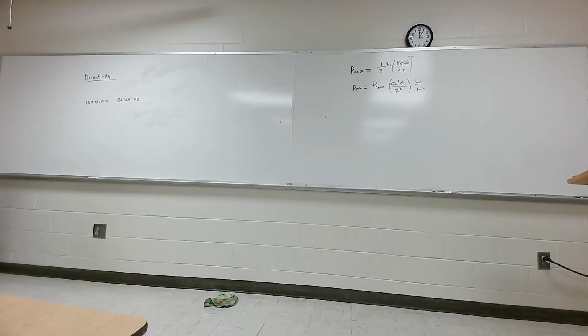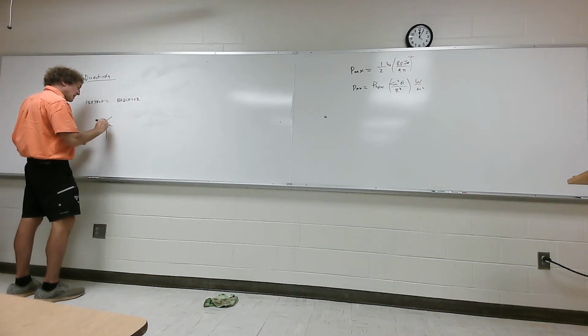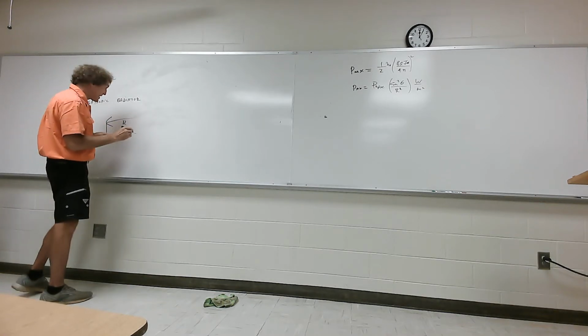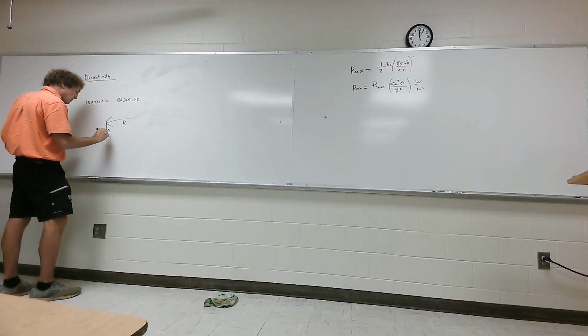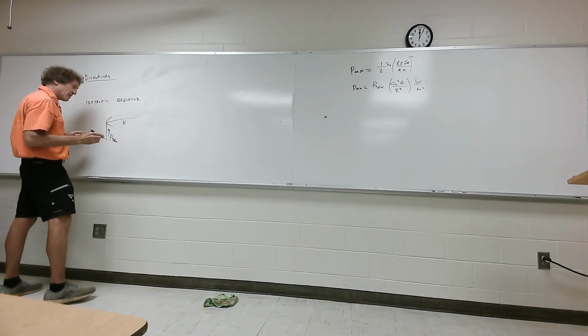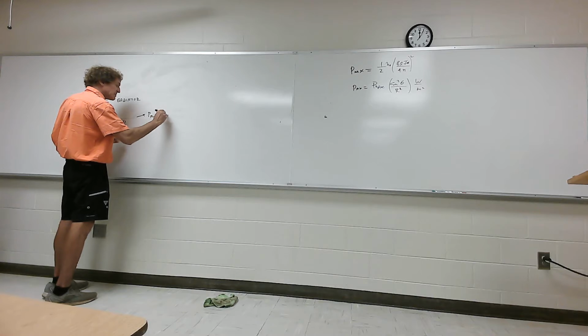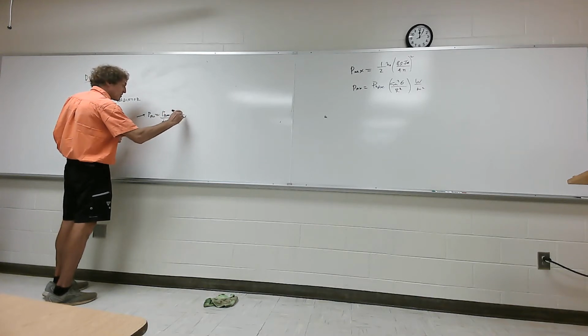Do y'all follow me? So for an isotropic radiator, if we come out a distance r away and we're transmitting a total power P transmit, then the power density, P av, is just equal to the total transmitted power divided by the surface area of the sphere, in watts per meter squared.